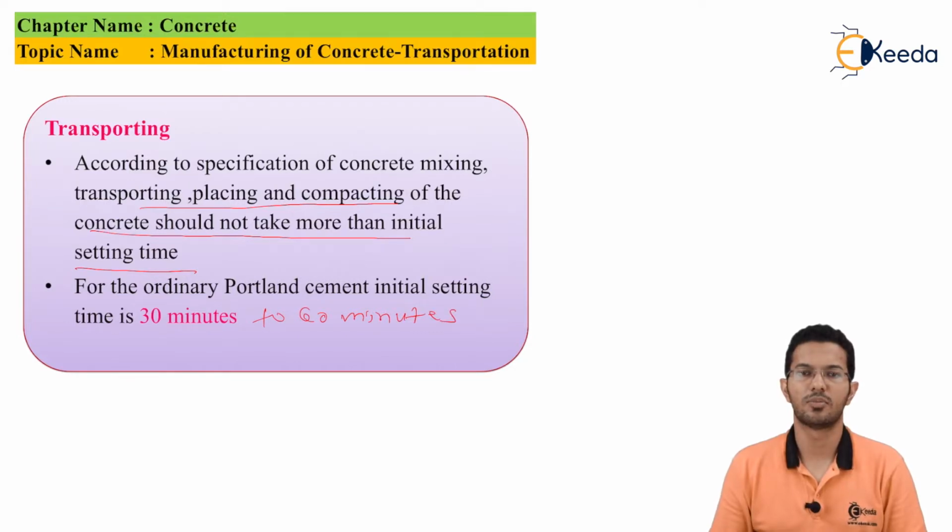At a central or portable ready-mix plant, concrete should be discharged from a truck mixer or agitator truck within 2 hours. If non-agitating transport equipment is used, this time is reduced to 1 hour.